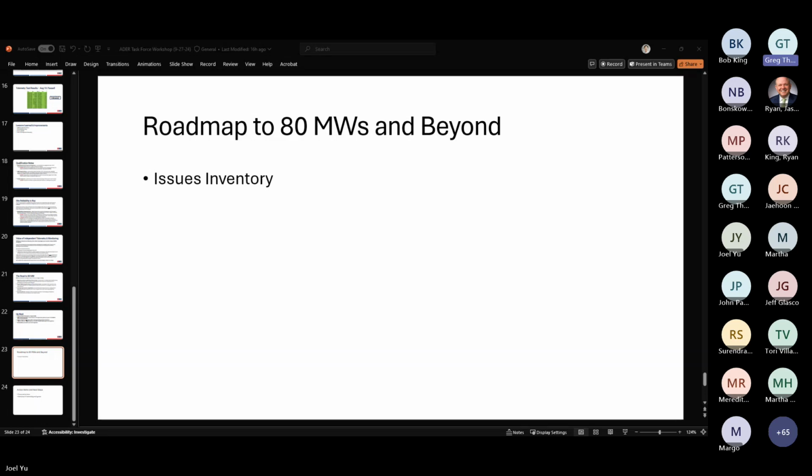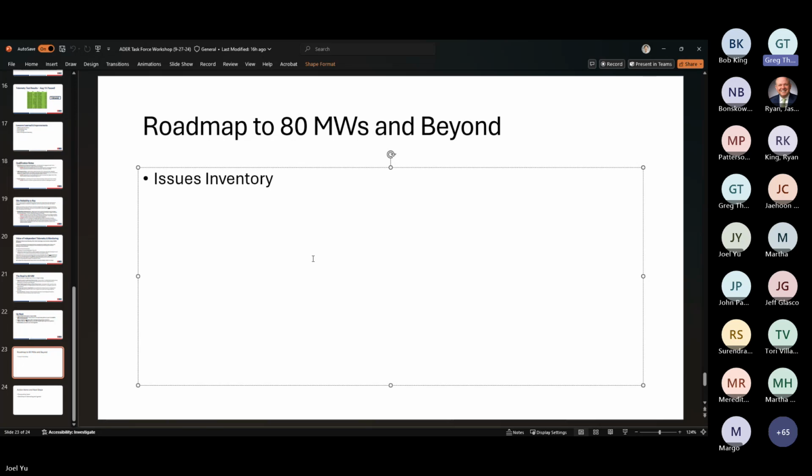You can get a lot of value that is complementary to the use case of the customer. Said another way, batteries are very excellent providers of PFR, as we see on the wholesale side. When extended to residential storage solutions, they can serve all of their goals: reduce grid usage, extend the use of solar, and provide primary frequency response.